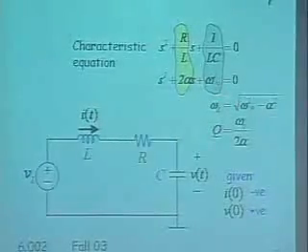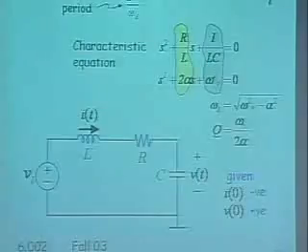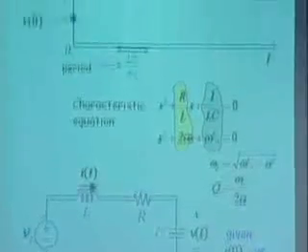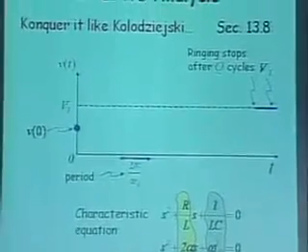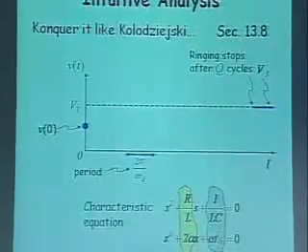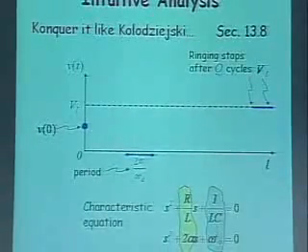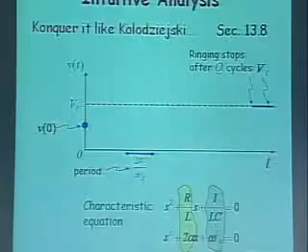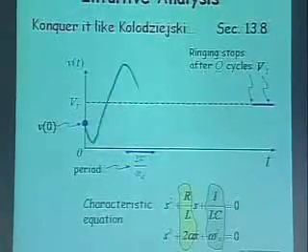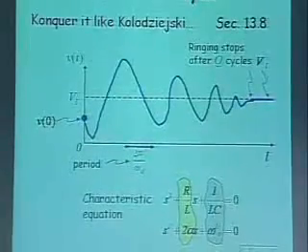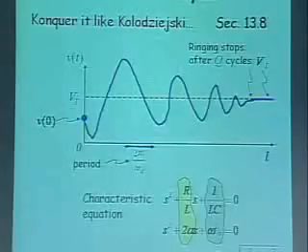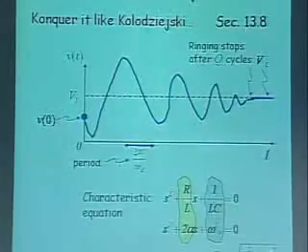Omega d gives you the frequency of oscillations. So my frequency of oscillation is now known. From Q, I know how long it rings. So I know it rings for about Q cycles. So I know that ringing stops approximately here. And then I know that between the start and end point, my curve kind of looks like this. Something like this. Right there, we're 95% of the way there.